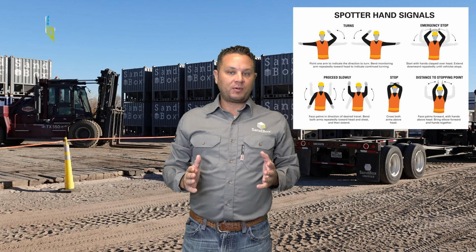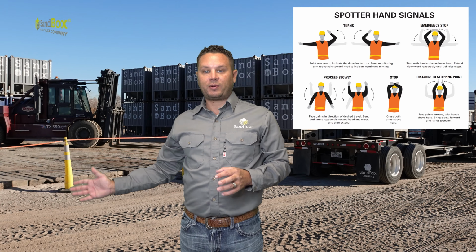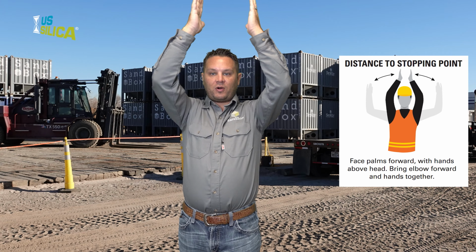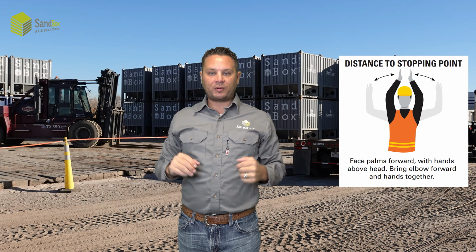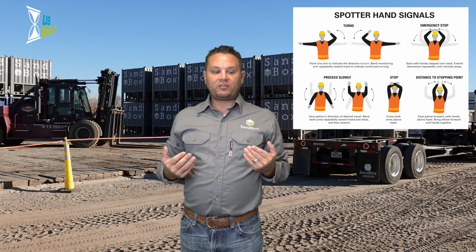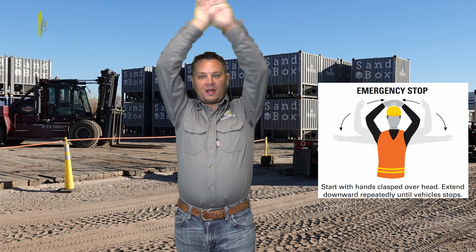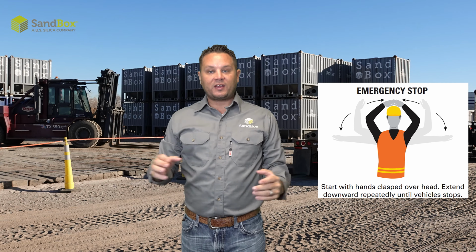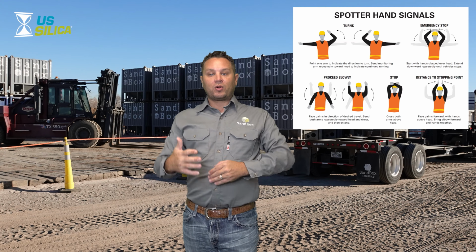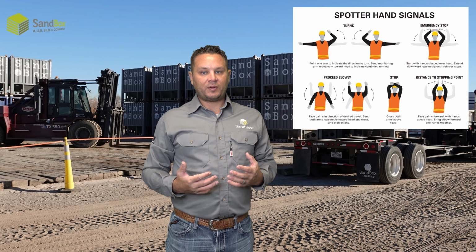Now, if we're backing up a driver in a specific area and we're trying to get the driver as close as possible to something, we can use our hands to indicate how far away they are from where we need them to park. If for any reason you ever need to emergency stop a truck while backing up, you will wave your hands and cross them. This will indicate that they need to emergency stop. So, these are the hand signals that we're going to use when we are out in the field and trying to move around a piece of equipment.